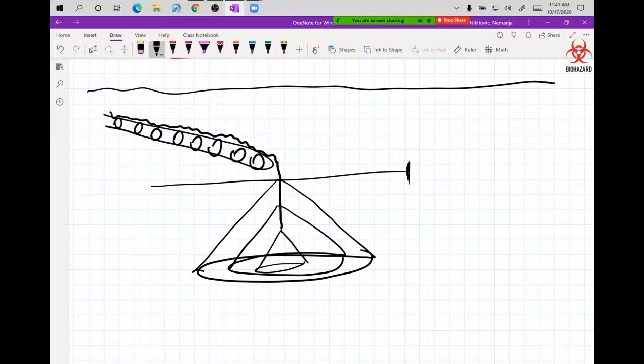So you can't really do that. Maybe the bird flies through and interrupts it and shuts off your conveyor belt, and you are only on the first stage of filling it, let's say. So bird flew by. So there are a lot of reasons why you do not want to use photo sensors to make a cutoff at the specific height.